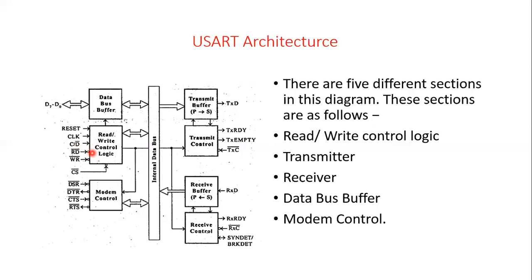This input register checks the ready state of a peripheral. The register is addressed as an input port when the C/D bar pin is high. It has the same port address as the control register. Then data buffer. This is a bidirectional register, can be addressed as an input port and an output port when the C/D bar pin is low.